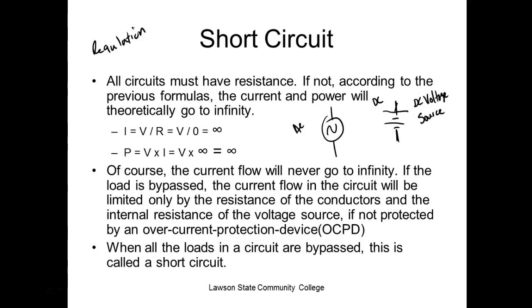In the power system in your car, you have an alternator, and then you have what we call a rectifier assembly. That's an assembly that converts AC to DC. Your car runs off DC. Y'all understand that? So your alternator generates AC. Then we have an electronic circuit we call a rectifier circuit that converts it from AC over to DC.